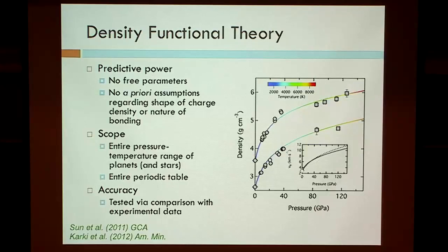And as you hit the sample with higher and higher velocity impacts, you map out this set of thermodynamic state points, all of which together combine to make the Hugoniot curve. And these are two examples here for two particular materials, starting from a molten material preheated to a liquid at 1 bar. We'll come back to that on Thursday.